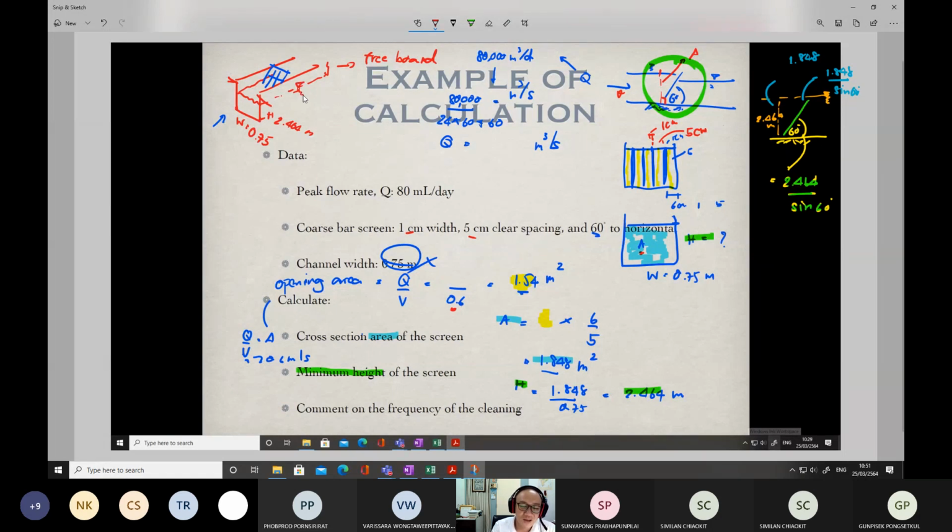So this is just the water level, so it's up to here. Whatever values you determine are basically the water height, not the channel's height. If you want to leave some space to prevent water overflowing, or by accident water coming out of the channel or spilling over, we have to leave some space, and this space is generally called a freeboard.